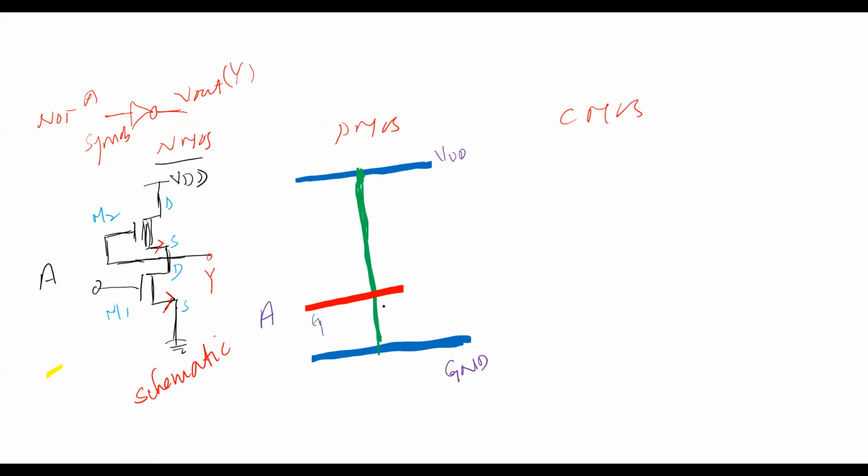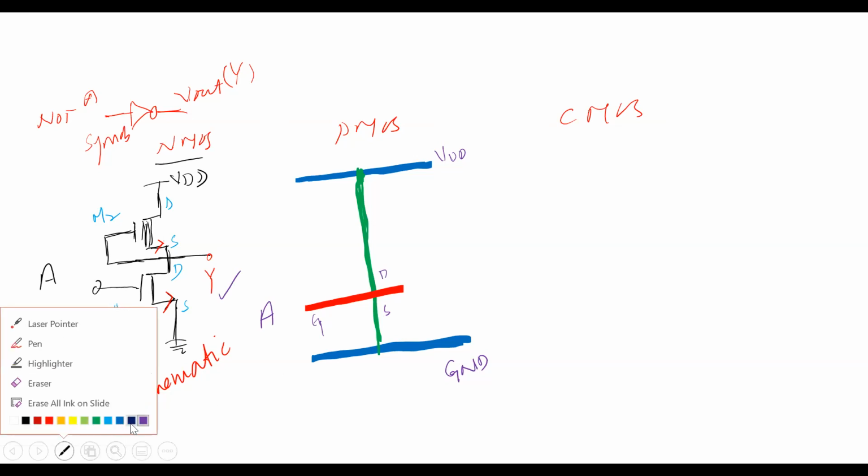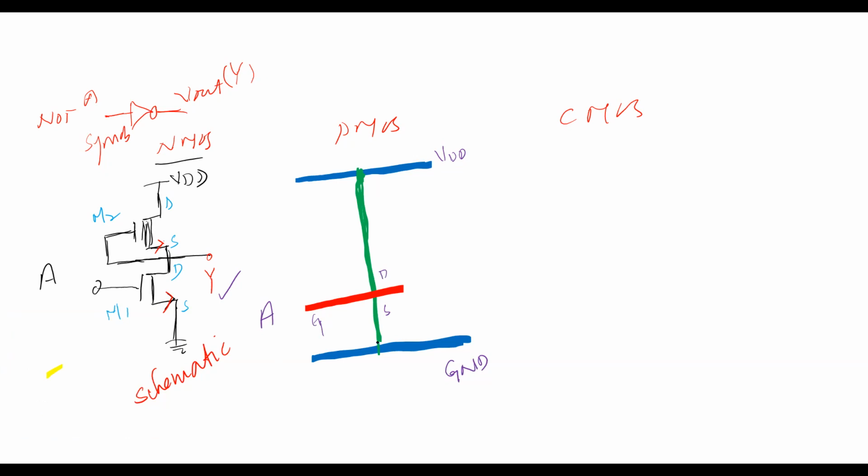Okay, and this becomes the source, and this becomes the drain. As you look into the schematic, the source is connected to the ground. Am I correct or not? Yes, sir, the source is connected to the ground, but the N diffusion layer and the metal layer are two different materials. To join them, one contact cut is required. The color of the contact cut is black.